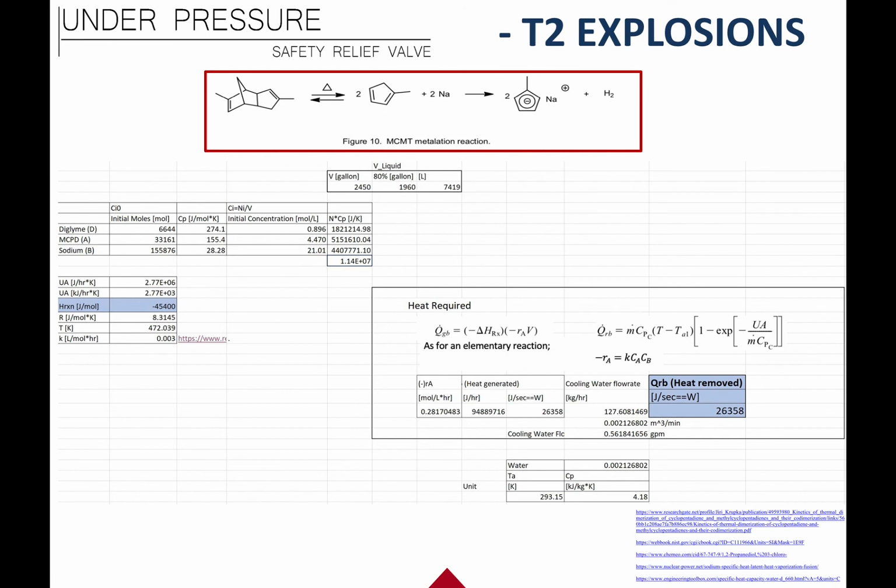We took into consideration the chemical reaction occurring in the system, and used knowledge from chemical reaction engineering to solve this problem. We used this equation: the heat generated equals the heat of reaction times the reaction rate times the volume, as our basis of solving for the heat being generated. The heat of reaction and volume are both values gathered from our resources, and the reaction rate was calculated. The reaction occurring is a first-order elementary reaction, and the reaction rate constant was another value from our resources, while the concentrations of A and B were solved from the information given in the article.